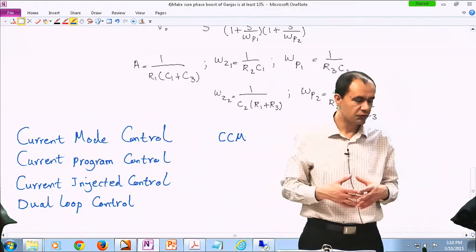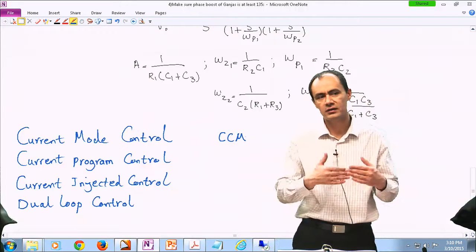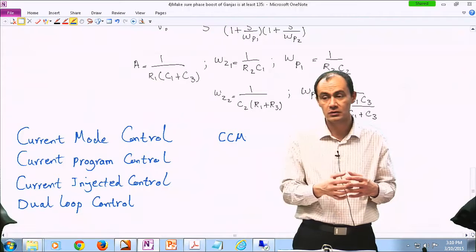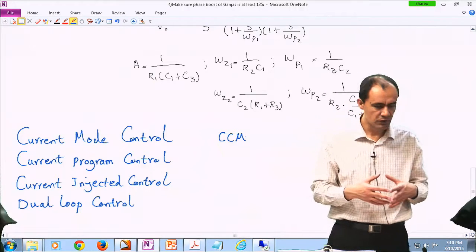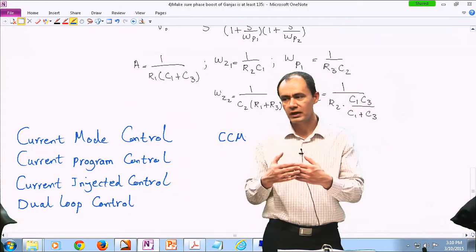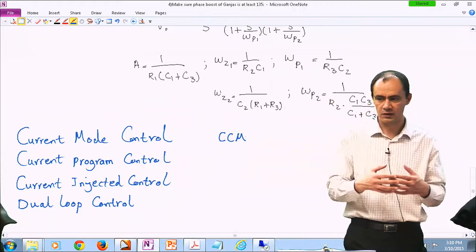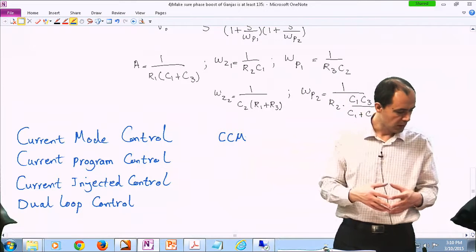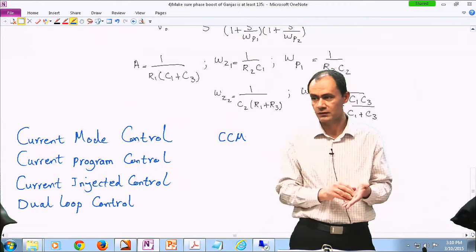What we have learned so far, now that we have a second control algorithm, everything that we have covered in terms of control is called voltage mode control, okay? So what we have done so far, like for instance this design that we had, is we are trying to regulate the output voltage, which is the voltage of the capacitor, one of the states in the system. But we don't even care about the other state, which is the current of the inductor.